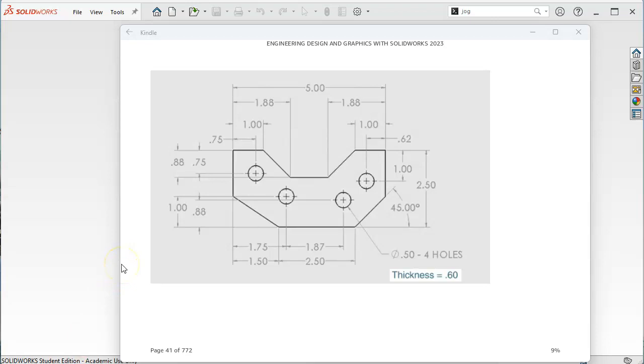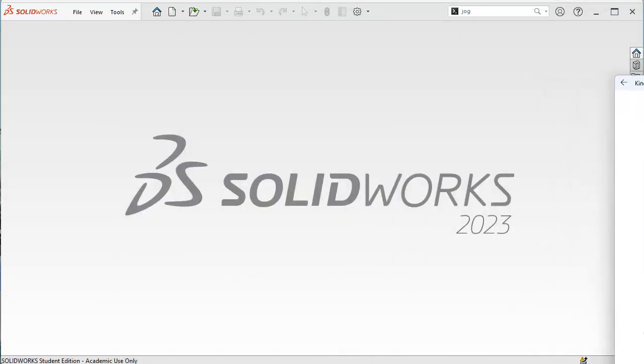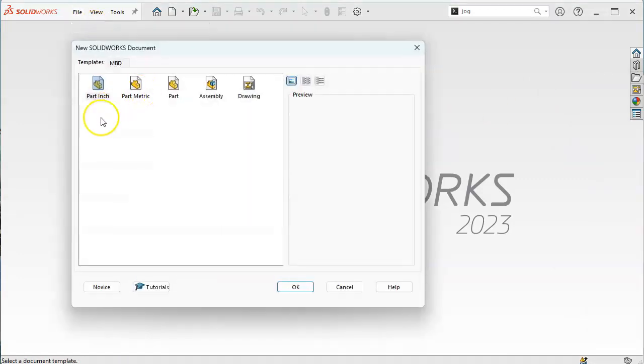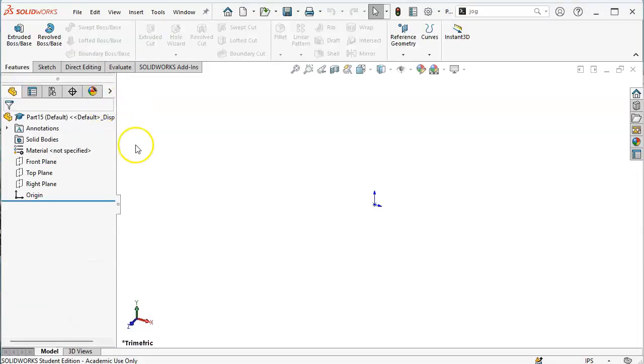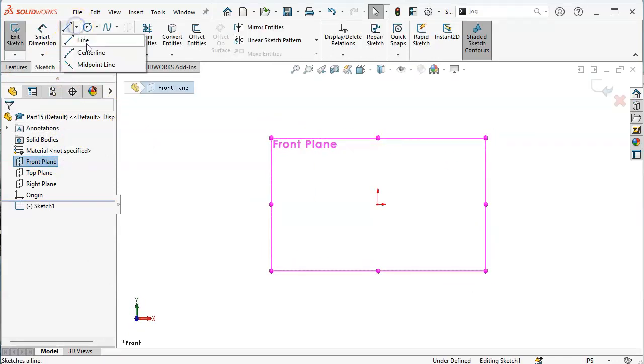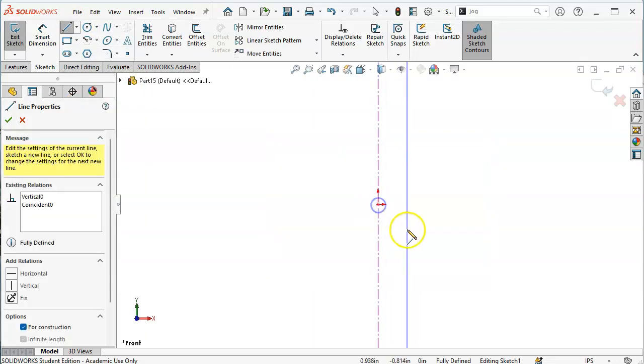Okay, our Chapter 1, Project 16 has symmetry, so we're going to use that to our advantage. We're going to keep with the optional on this, so be aware of the different techniques. We are in inches here. When I'm doing symmetry like this, we'll open up the sketch. I would like a center line, I would like it vertical, and I would like it infinite length.